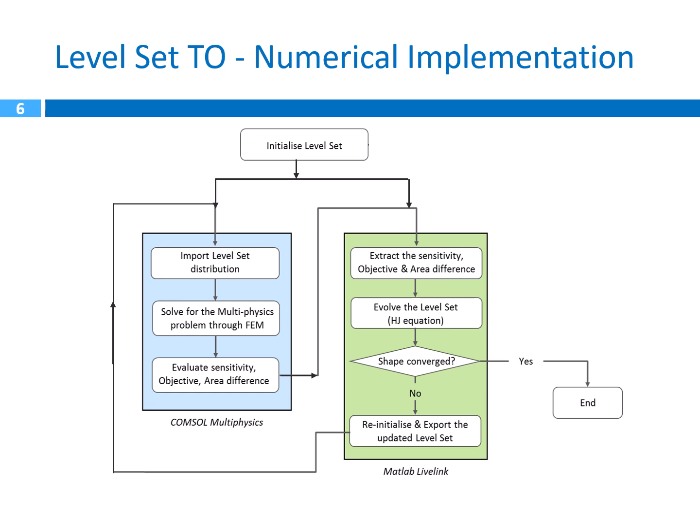In the case of the level set method, there is an additional step which is called reinitialization. As the shapes progress to the new shape, the level set, let's say you are having cone shapes, as you propagate it, the slope of the cone may not be one.